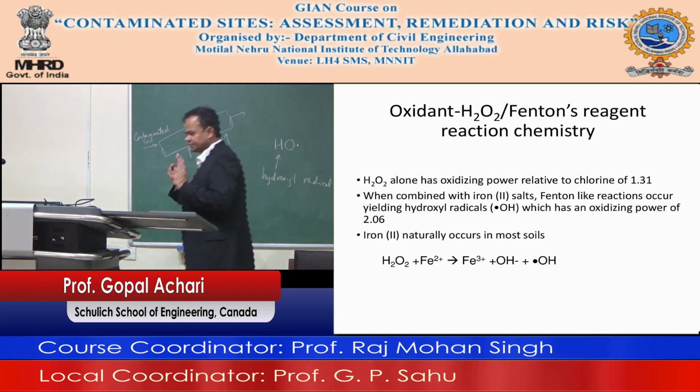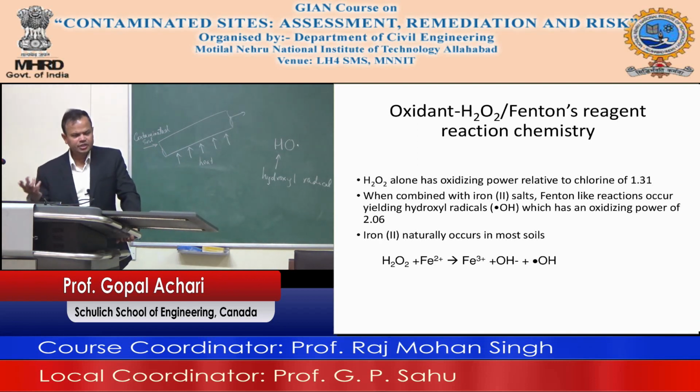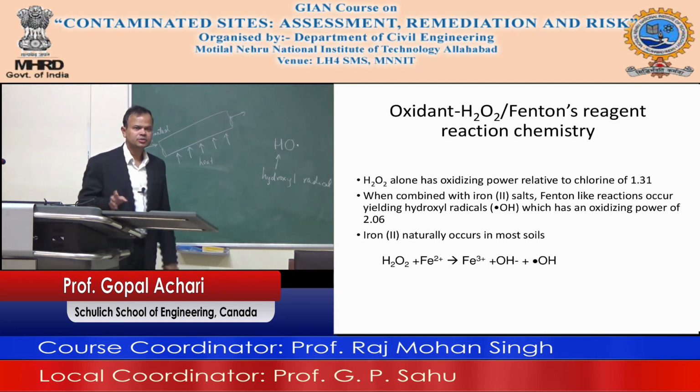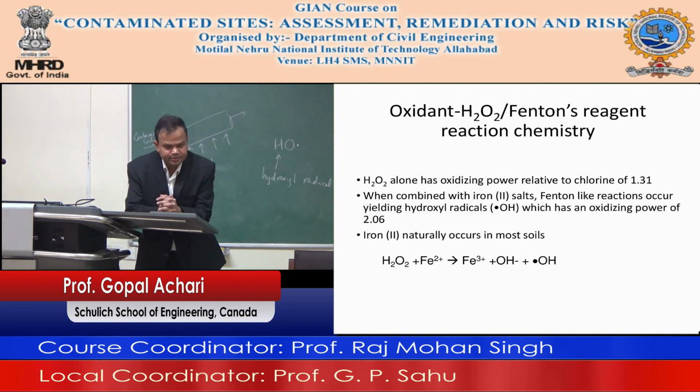Okay, but hydrogen peroxide is not that expensive. Iron is usually present in the soil, and many times they're able to harness it to get to the reaction, and it works quite well. It is a very well-known technology. Okay, use application of hydrogen peroxide to treat soils. So if you have hydrocarbons, you want to do it, that's one way to think of it.